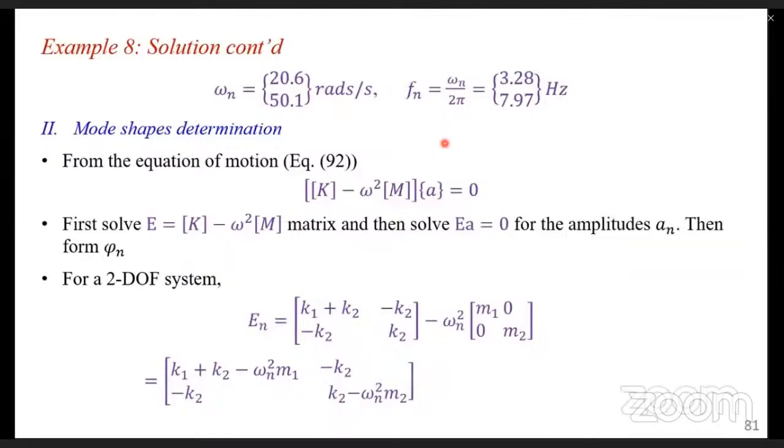Of course, even from the code, like when we talk of L over D, you are given for a slab that it should not exceed this value. For a building, you say this should not exceed a certain value. Otherwise, after that, it's now a serviceability limit state. Even if the structure may not collapse in the ultimate limit state, in terms of serviceability your design may have failed.